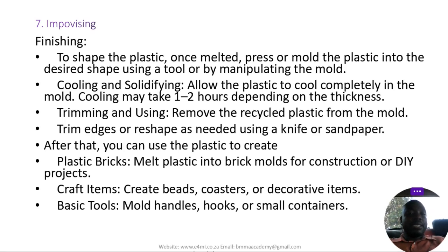After melting, we get to the finishing part, where we start shaping the plastic. Once it has melted, we can press or mold the plastic into the desired shape using a tool or by manipulating the mold. We can then cool and solidify the molten plastic by allowing it to cool completely in the mold. Cooling may take between 1 to 2 hours depending on the thickness. If it's too thick, it has to take a little bit longer, but if it is just thin, it can take even less than an hour.